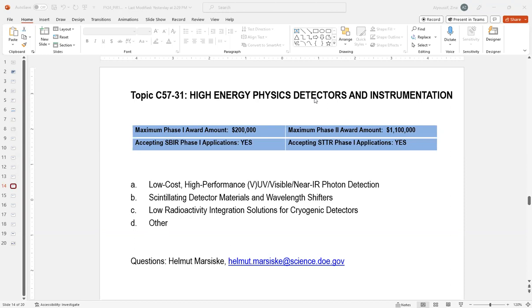No, typically a particular application would focus on a particular area within the spectrum. As I say, if you're dealing with noble liquids, you would be looking at wavelengths below 200 nanometers. For sensors that read out scintillating materials, you would be looking more in the optical.